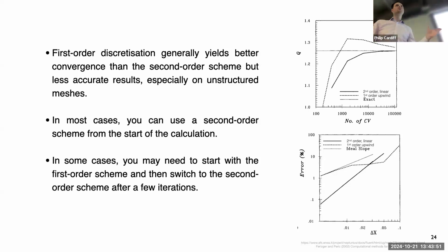In practice, what I would do is I just start with higher order schemes. If it works, great, I don't have to think about it. If it doesn't work, then I go back and run with a lower order scheme and then restart with the higher order scheme. So that's the idea. So you have to be very careful. Sometimes, for some of the equations, like the turbulence equations, you can solve them at first order. Maybe it's okay, they don't affect the solution. Just be very careful.